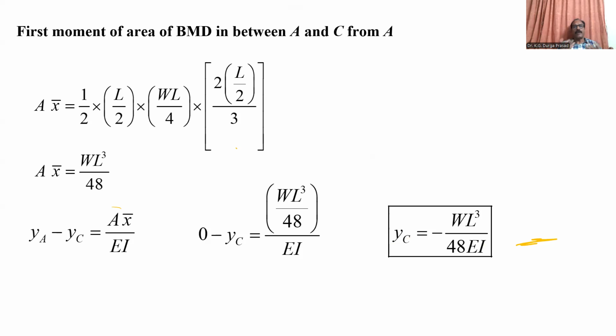So you are having some doubt. Suppose there is a beam subjected to a number of point loads and UDL. In such cases, I advise you not to attempt these two methods, like moment area method or double integration method. In such cases, better you can follow Macaulay's method. Any doubts? If you have any doubts, please feel free to ask me. I will clear all your doubts.